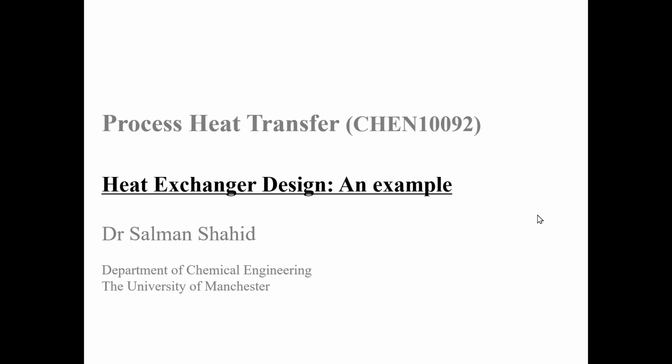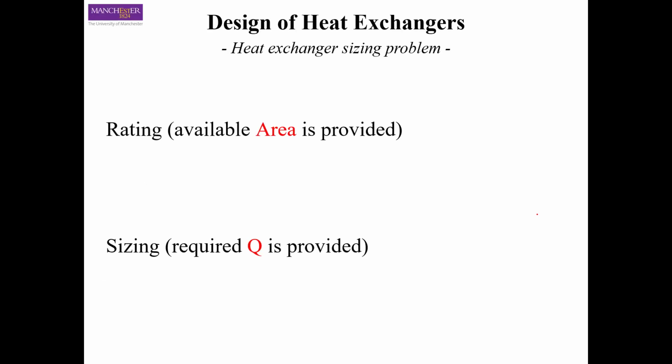Okay. So when we are talking about design of a heat exchanger, we said that we are talking about either one of these two problems. So we have either the rating of a heat exchanger, and by rating we mean that the area of heat transfer. So we normally do rating for an existing heat exchanger, so it means that the area of the exchanger is already known to us, and we want to know that if we are changing temperature or conditions, is this area going to be sufficient to transfer that much of heat load.